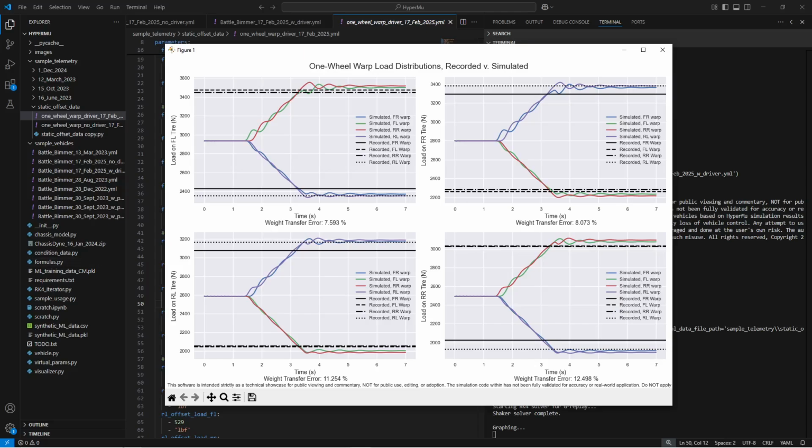Another factor affecting accuracy, possibly the most important one, is HyperMu's tire model. Tire stiffness and damping, as you're probably aware, is highly nonlinear, affected by tire pressure, displacement, and even things like camber angle. Despite this, HyperMu has been using a linear tire stiffness and damping model until now, partially because it was a quick start to get the simulation running, but also because there haven't been significant correlation tests until now to expose it as a significant source of error.